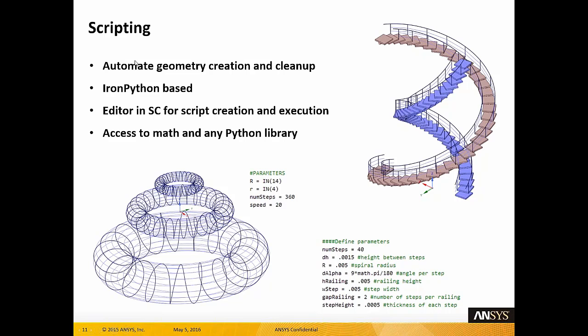But again, the whole point of scripting, I would say the most valuable feature, is it can be used to automate your use of the software. You can run a script without needing to make the mouse clicks, without needing to make the selections. Now, to cover some of the details of scripting, it's a text-based interface to SpaceClaim, based in this case on Python. So if you're at all familiar with that, it's very lightweight and easy to use.